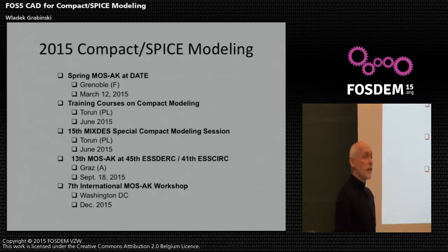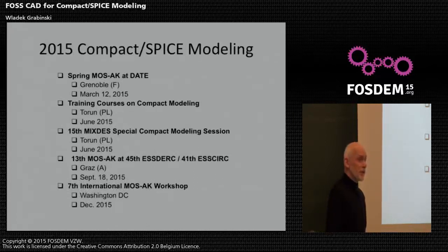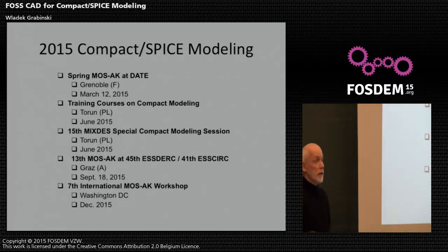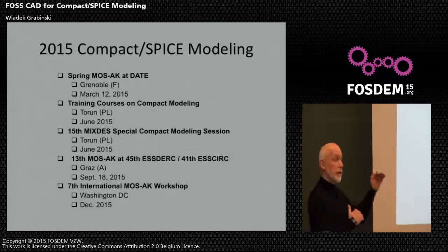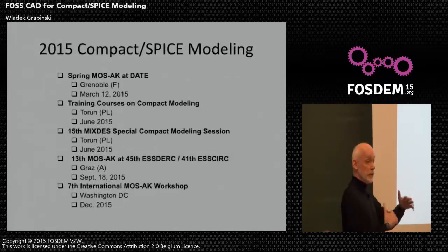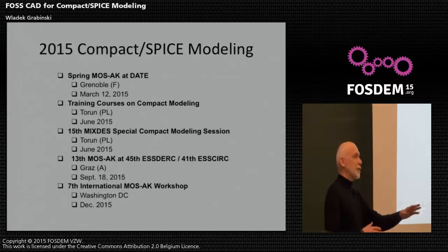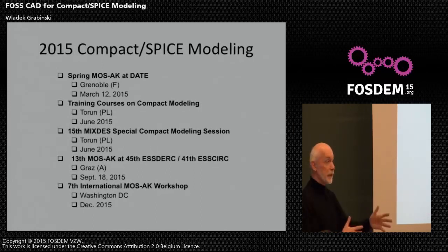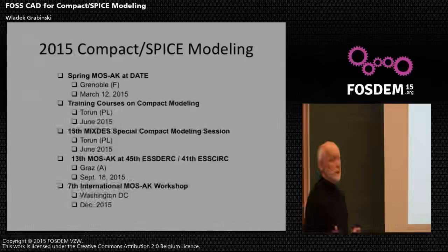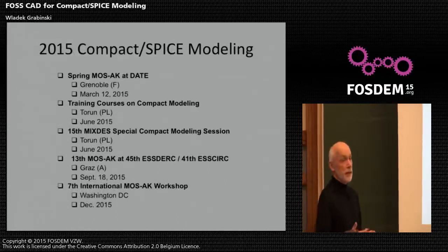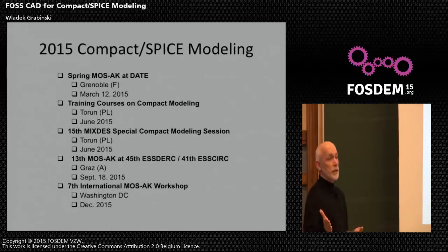The question was about Verilog-A standardization for schematics. This is a very important question, but we do not have a solution. There was discussion to use this type of high-level behavioral language to describe not only devices, but schematics or netlists. ngSpice uses, I don't want to say old, but the standard SPICE input language, which is a little bit outdated. Quarks has its own. So there is open discussion also within industry to have more flexible input formats for netlists and schematics. And very likely Verilog could be a solution. But yes, please.